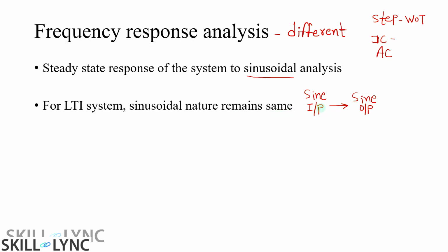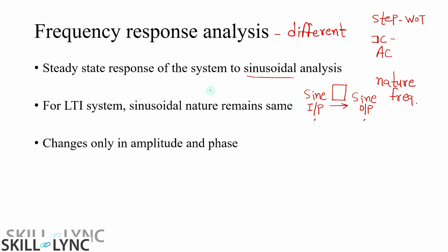Then you may be wondering that if we give sine input and if we get sine output, what is the change the system is making over here? Yes, there will be certain changes. They are not going to be exactly equal, but their sinusoidal nature and the frequency are going to be same. So what are the changes? Changes are only in amplitude and phase, right?